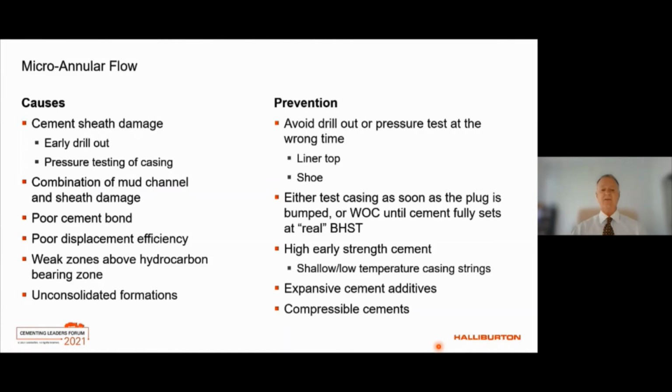Steps to prevent inducing a mechanism for sustained casing pressure include: avoid drilling out shoe tracks and liner tops until the cement is fully set. Pressure testing of tubulars post-cement placement should take place as soon as the top plug lands or the cement is fully set at the real bottom hole static temperature. Additional considerations should include the incorporation of post-set expansion additives in the cement to counteract cement shrinkage, as well as compressible or foam cement solutions.